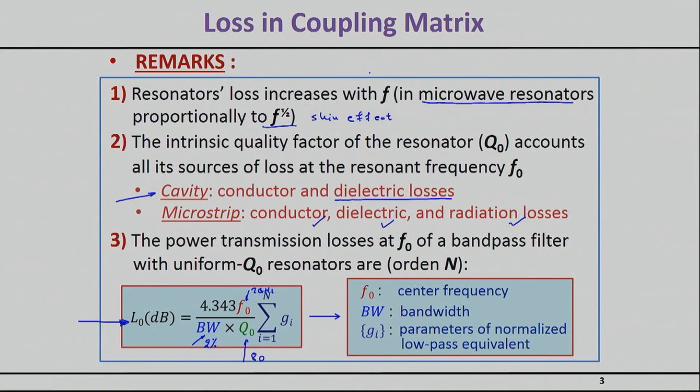You just apply this equation here where these G parameters are basically the G parameters related to the type of filter you want to build. Now, it's true you will not always have the G parameters, but for many cases you will have some G parameters you can rely on. And if you do that, again, you will get a very accurate estimate without building anything, without simulating anything. So you can very quickly make that assessment.